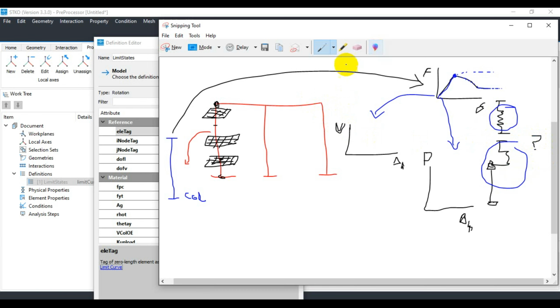And we have some predefined red line in terms of the limit state that is required to consider in this model. So let's say we have this surface and we are telling OpenSees, if my shear is going to the right side of this curve, trigger the warning and collapse that member by its performance.